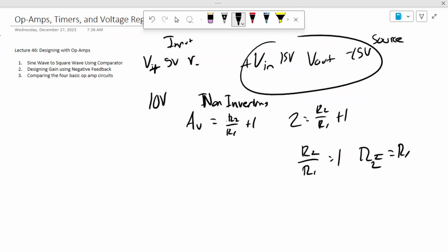So all that is to say, if I have a non-inverting amplifier feedback loop and I want to double the voltage, all I need to do is pick two resistors that are equal to one another. So to design that, I just have my plus, my minus, my output. And remember, if it's non-inverting, this is going to go to the battery, which we said is 5 volts.